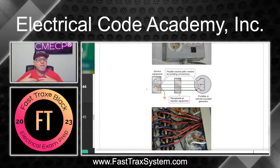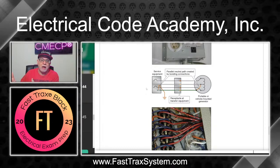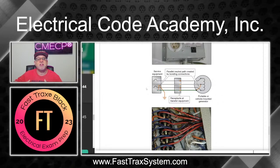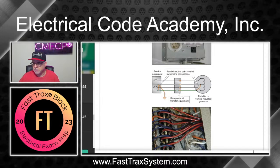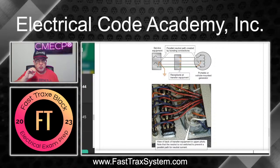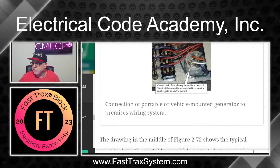So typically a floating neutral generator would be what you would use on a dwelling, whereas a bonded type generator is what we would want to use as a standalone application, okay? And now I'm not going to get into modifying generators. We'll leave that for you to search out and find for yourself. I'm not going to get into that liability trying to explain that here.